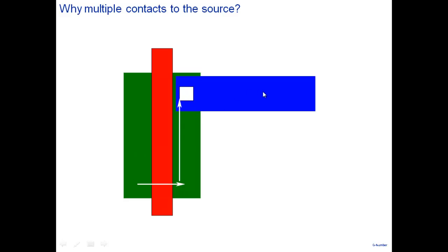This is metal, very low resistivity. So current comes in here, and this is the contact. So current comes over the metal one, and this is a contact. So it will go through the contact into the N plus here. And then how does the current have to flow? Current has to flow from, let's say this is source or whatever drain, into the source side. So it will flow like this, right? But it has to also flow like this here, this entire region here. So the current would be going like this, like this, like this here.